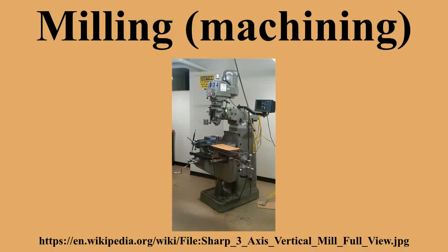Van Norman specialized in ram-type mills through most of the 20th century. Since the wide dissemination of CNC machines, ram-type mills are still made in the Bridgeport configuration, but the less common variations have died out, the work being done there by either Bridgeport-type mills or machining centers. Turret mill: more commonly referred to as Bridgeport-type milling machines. The spindle can be aligned in many different positions for a very versatile, if somewhat less rigid, machine.